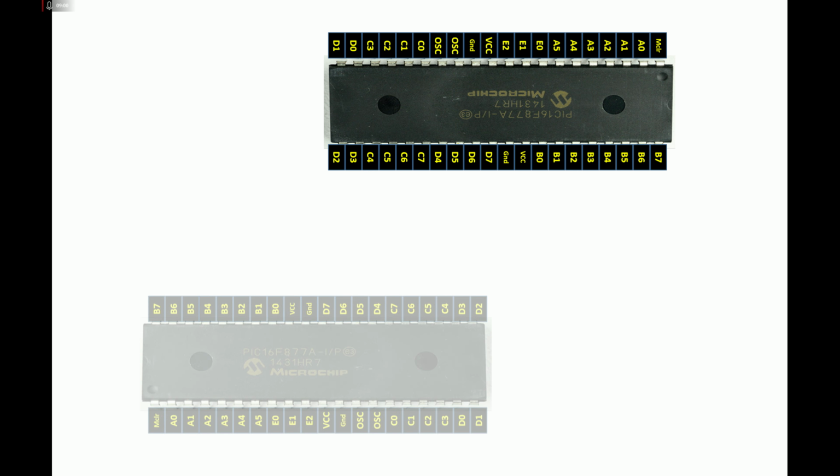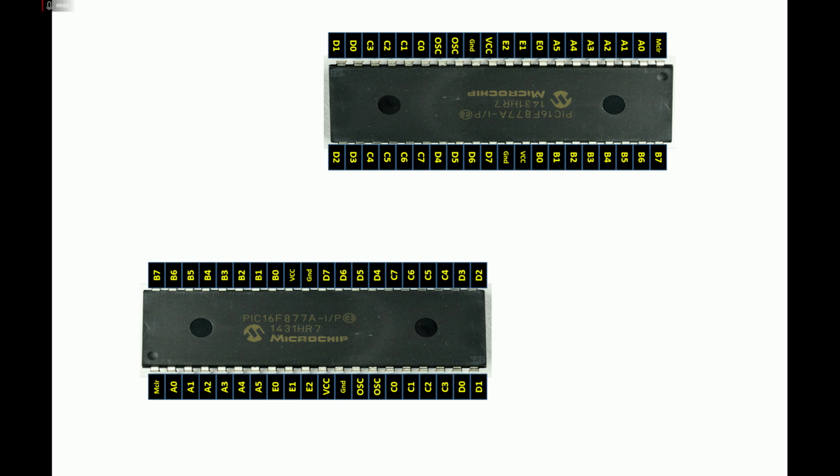Finally, I give you a demonstration of the PIC16F877A. If you guys are interested in PIC, then take a look at this slide as well. Suppose we have two PIC16F877A microcontrollers. I'm just taking this as an example. In the PIC16F877A, you have one UART port and it is located at pin number 25 and 26. Pin number 25, that is pin C6, is the TX. Pin number 26, that is port C, pin C7, is the RX.